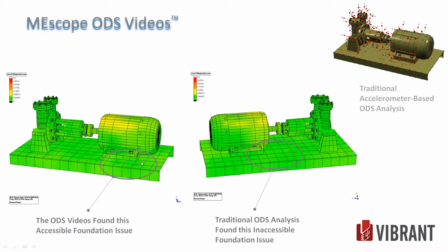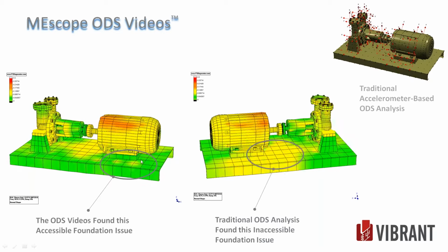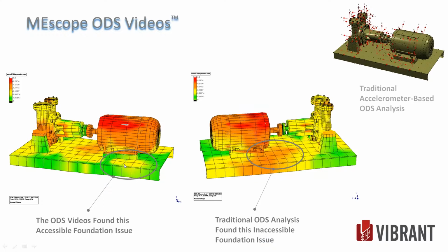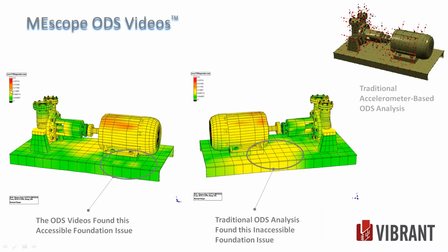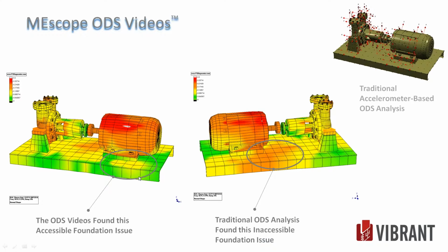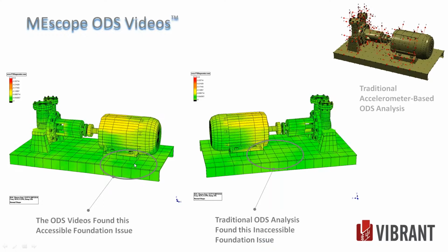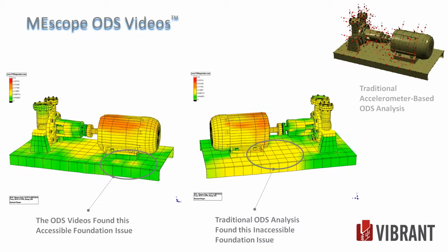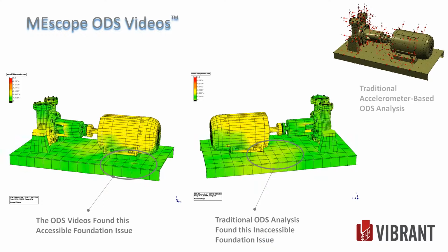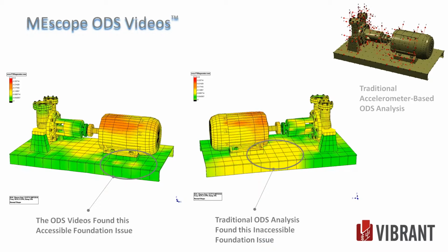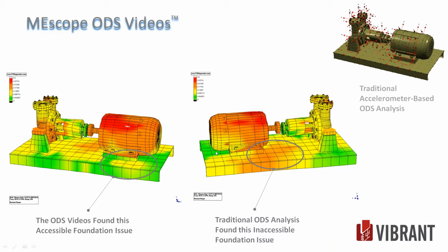So there was some motion right here that we're picking up in the deck where it's going yellow, and 0.15 inches per second, something like that. That's about 3 times what you'd expect from a deck or a foundation or something that's supposed to be solid. Anything over 0.05 inches per second is usually a problem, or the start of a problem.